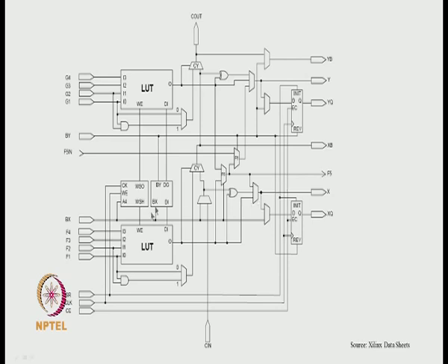It may happen that you assign the pin somewhere here, and some lookup tables are close to the pin and some are away from the pin. So the read latency may be different for the different lookup tables, and you will see this if the read is not synchronized, which is usually the case.